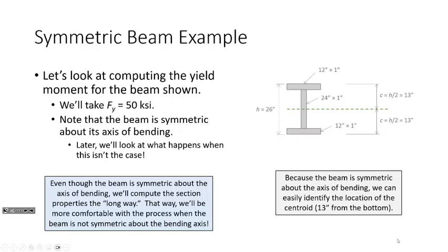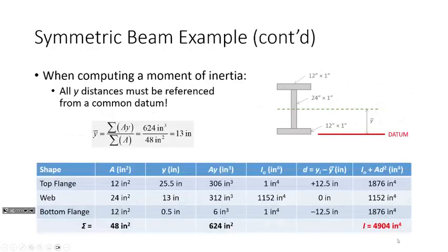Okay, so there's a lot here on this slide, but if you had me for 216, you've seen this before. The first thing that we're doing here, so I have here the I shape, is this first half of the table, which is going to be about computing the location of the centroid. Now everybody in here should be familiar with that from statics, right? If you want to compute the location of the centroid, it's the sum of AY divided by A. Y'all remember that from statics? I'm sure everybody's good with that? If not, don't worry, we'll take our time with it.